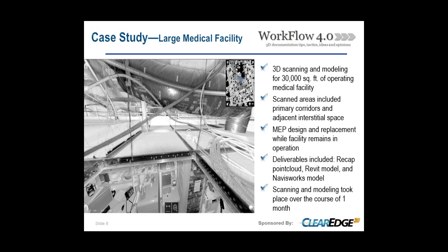The point, I guess, of the scanning was as-built mapping for existing conditions to do a design of MEP in place so that they were able to design and replace without ever interrupting operation of the facility. And what we were handing off to the client after scanning and modeling would have been a ReCap cloud, a Revit model for clash detection, and a Navisworks model. The scanning itself was 3 mobilizations, about 6 man days, and modeling took about 3 weeks in addition to that.